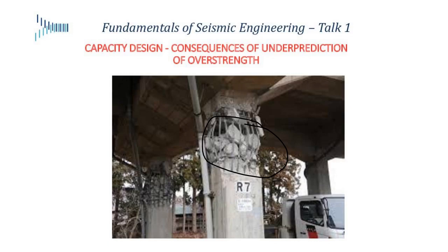The one difference I want to point out between an electrical fuse and a structural fuse is this. An electrical fuse will be destroyed and it will save the appliance. In our case, the structural fuse has to keep operating at that force level. The bending moment M has to be locked into the system.